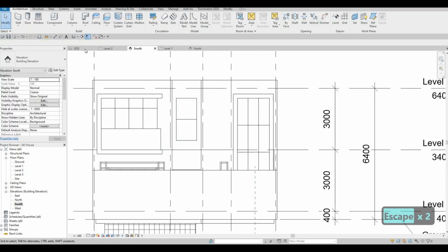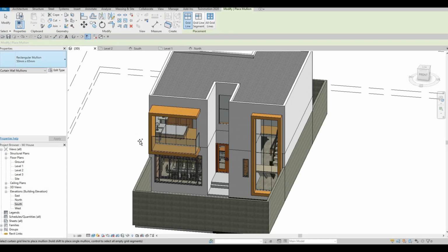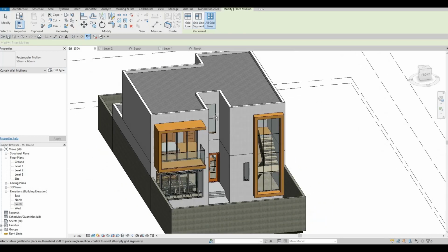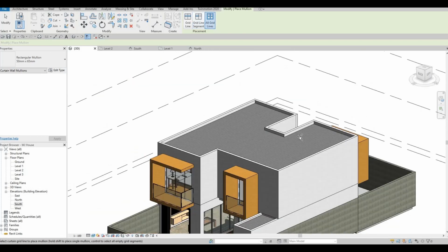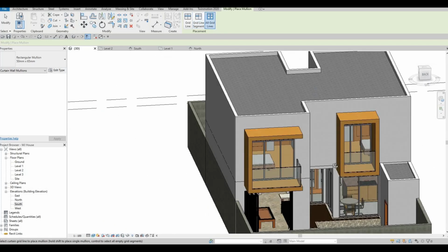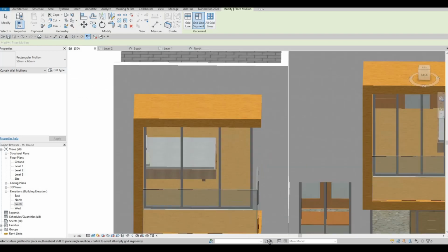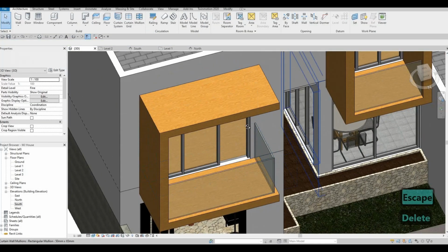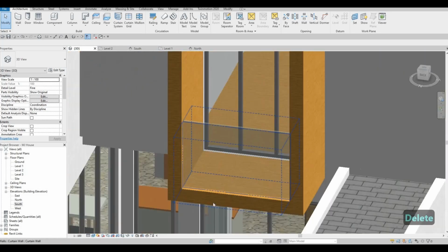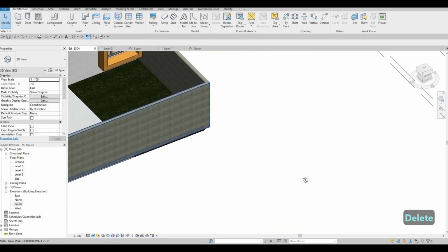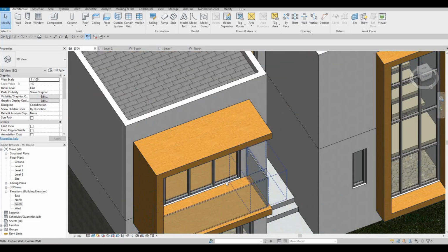something like that. Let's go to 3D, click on mullion, and then choose 50 by 65, and then all grid. Select that right there, also right there, and all of those. So in the position where you're going to put the glass door, you need to remove the one from the bottom, especially right here as well. You need to remove the one in the bottom, and also on this one. And then we need to insert the door.